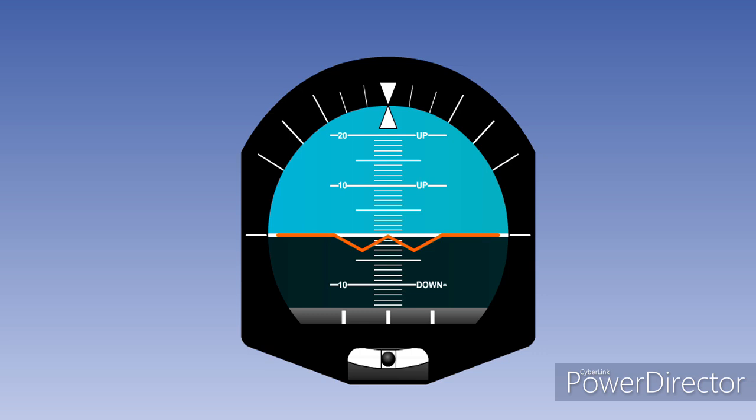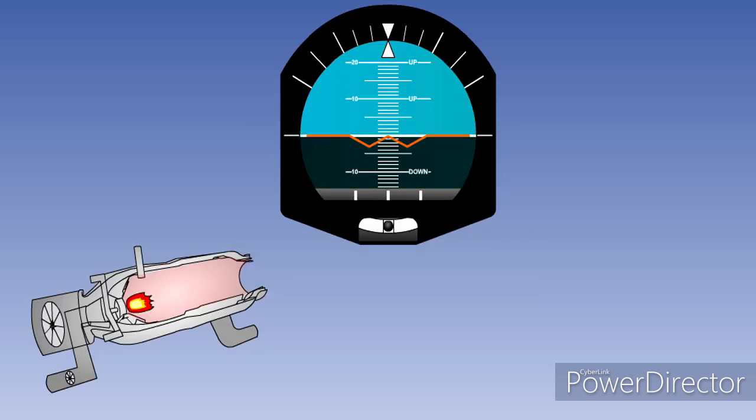Light aircraft may use ram air, a dynamic air pressure created by the aircraft's motion, to operate gyroscopic instruments. They can also use ram air heated by the engine exhaust gases or by a combustion heater to heat the cockpit and cabin and to demist the windscreen.